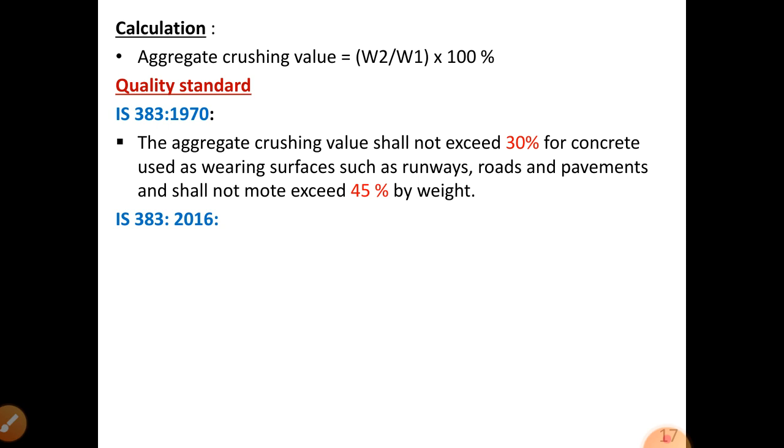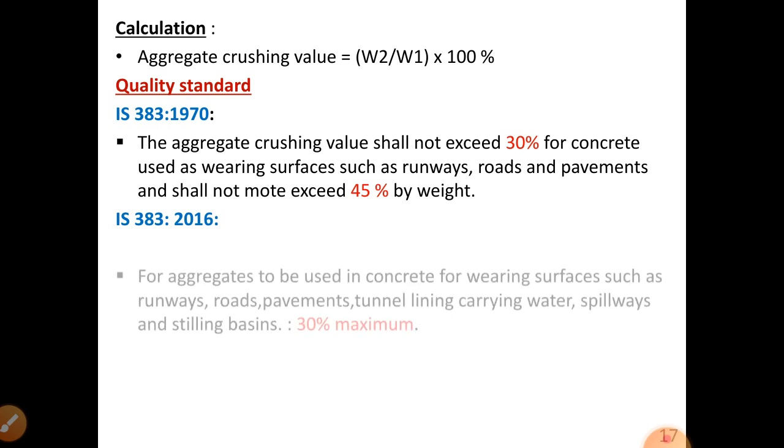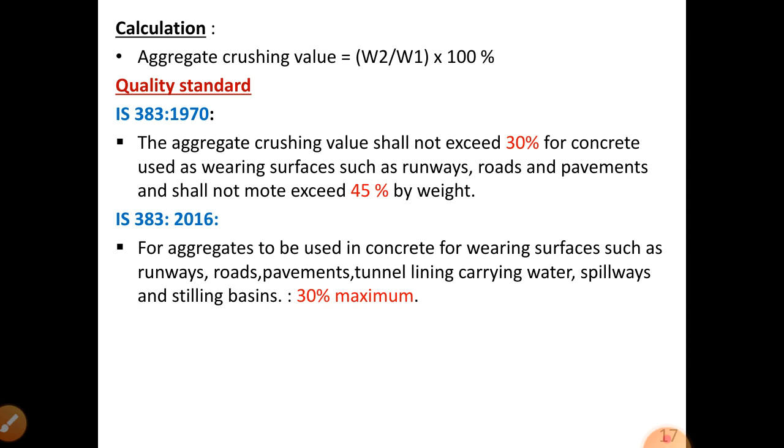In 2016, they say for aggregates to be used in concrete for wearing surfaces such as runways, roads, pavements, tunnel lining, carrying water, spillways and sealing basins, 30% maximum.